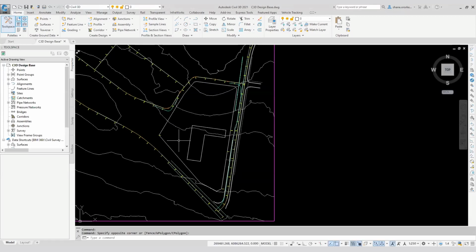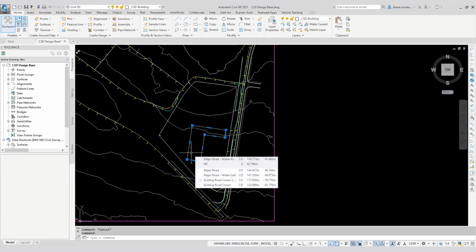So we have in this job here a surface, and I have an outline for a parcel of land that I'm going to design vertically. And I've just, to kick us off, got a polyline here for a building pad. So what I want to do is nice and carefully introduce what feature lines do, how they work vertically, and then how to use them.